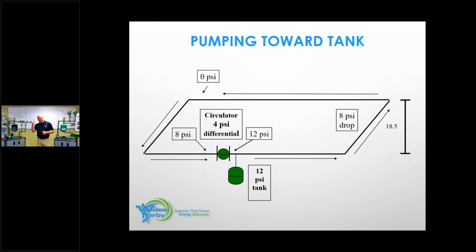That means that we have a potential to start stacking air bubbles on that highest level in the house and creating a no heat situation, because we're going to have air bubbles stacked there. We're going to be unable to move the air pockets, and you're going to end up with a no heat coil going out there purging the system.